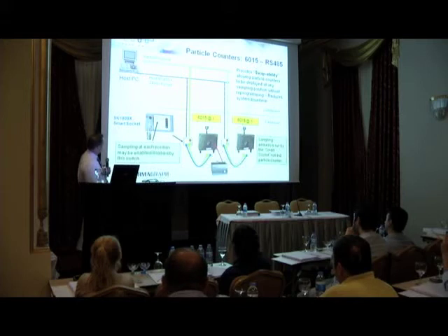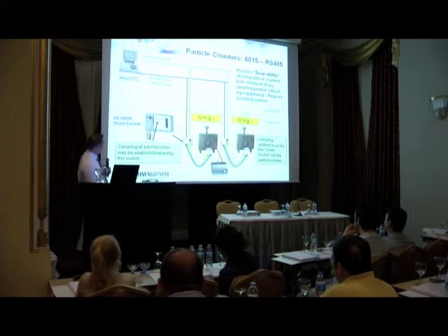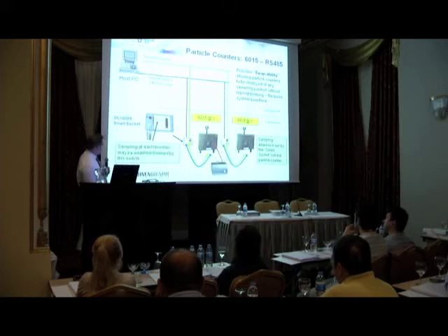to your counter. Whereas if you have an Ethernet counter and you move the counter from there to there, the computer thinks, even though the counter is there, the computer thinks you're still monitoring at this location. So with the 485 connection, you put the address into this device here, so you're always sampling from where you think you are, no matter what particle counter you put there.